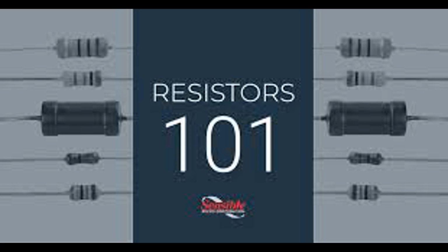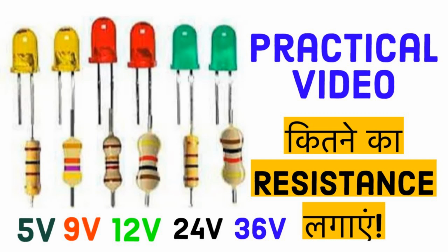Measuring high voltages. Purpose: Voltage dividers can be used to measure high voltages by scaling them down to a safer, more measurable range. Example: In multimeters, voltage dividers are used internally to allow the measurement of high voltages by reducing them to a level that the device can safely process. Power supply regulation. Purpose: Voltage dividers can provide a steady voltage level for low-power circuits. Example: A simple voltage divider can be used to derive a lower voltage from a higher one to power small circuits or devices.